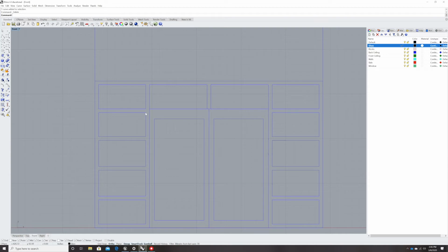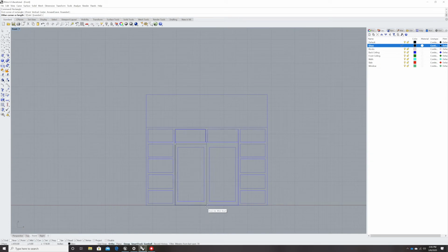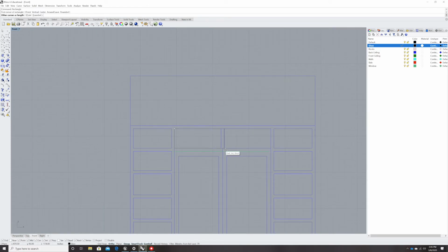And switch my layers real quick just so I can draw a different color there. Okay, switch back to glass. Here we go. So draw a rectangle for the door, the overall door. And I'm on that glass layer. Go from over here, because I want this whole thing to be made out of rectangles. So trace.